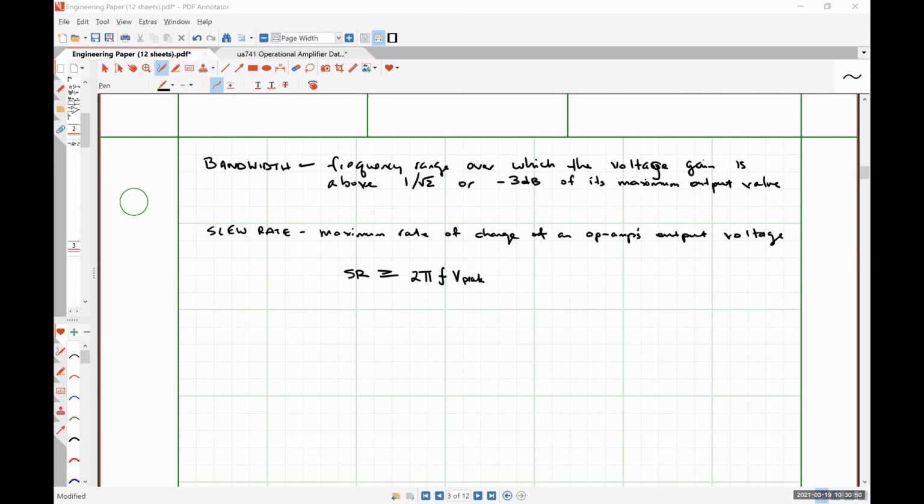0. Why? That's where it gets a little harder, okay? If you review the circuits 2 material for every one of these practical op-amp circuits that we did, it didn't matter what our R out value was, the output resistance measured looking into the output terminal was typically somewhere around 0. For an ideal op-amp, we effectively have a short circuit in parallel with this network, which is going to be exactly 0.